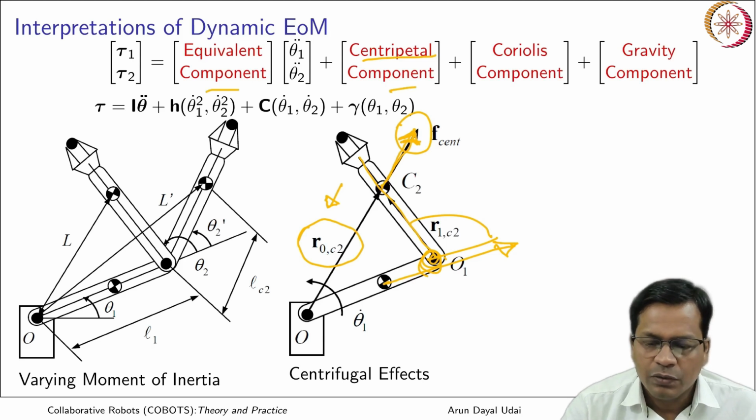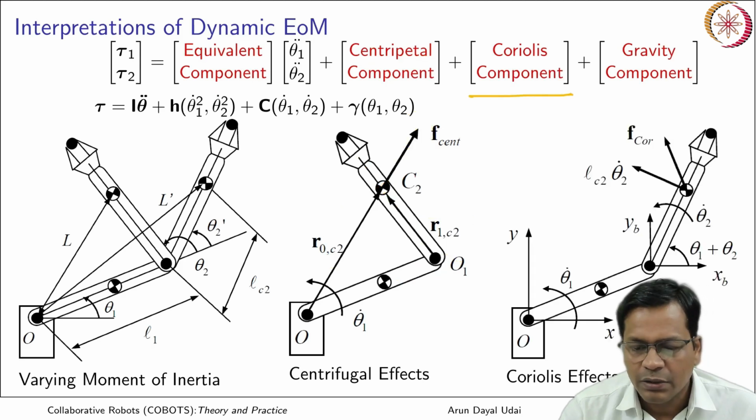Again, the Coriolis term, that is the second last term. You see in this case this link is very simple and it just has angular velocity here and mass is here. Whereas in the second joint, this causes motion to the second link. In this case it is both rotating and translating.